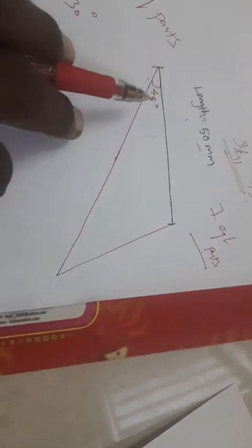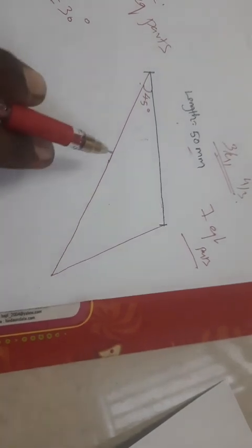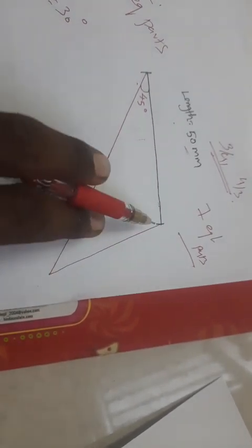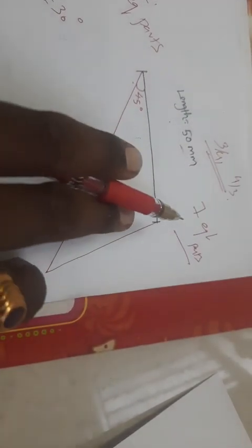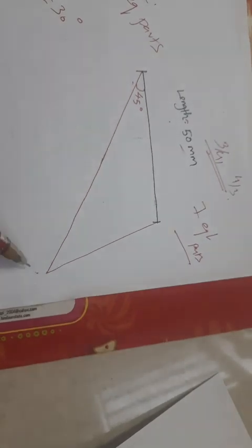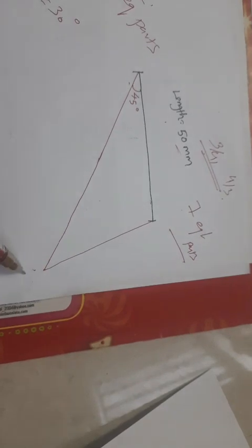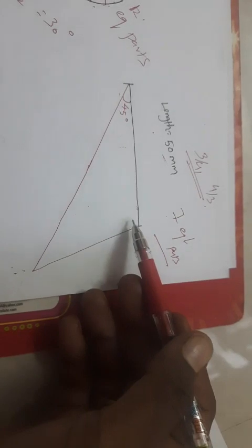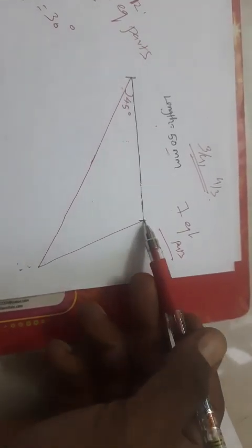How? Draw an inclined line from this point at 45 degrees, of distance 70 mm. How many equal parts am I going to split it into? Into 10. If I am going to divide this line into 8 equal parts, I am going to draw a length of 80 mm. If I am going to divide this line into 9 equal parts, draw a length of 90 mm. Now I am going to split this line into 7 equal parts, so draw the line of length 70 mm and connect the last two extreme points of these two lines.